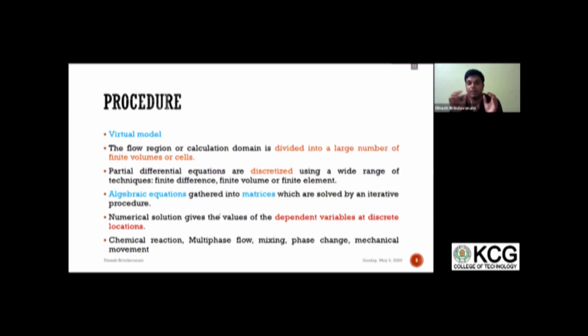There can be a native format and a neutral format. A native format is, for example, if you take a CATIA model, once you're done with your CAD modeling, the output is in the file format .CATPart. This specifies that the model is editable only in the environment of CATIA. So the CFD solver cannot use this kind of model. It should use only a neutral file format.